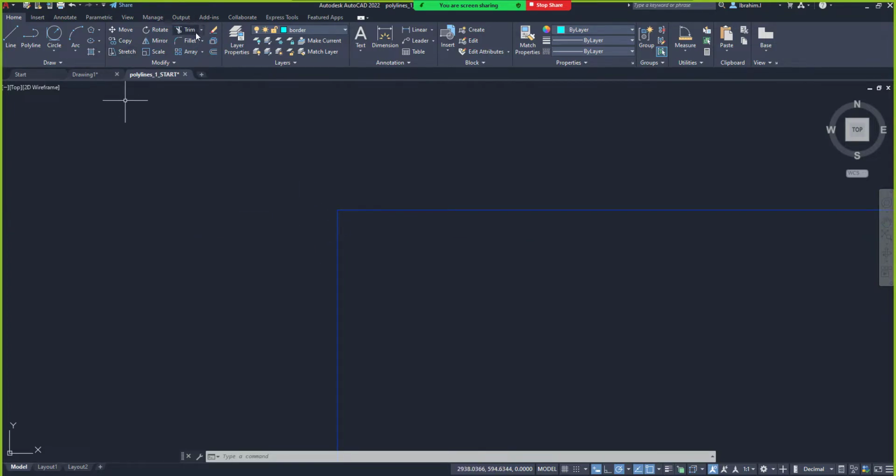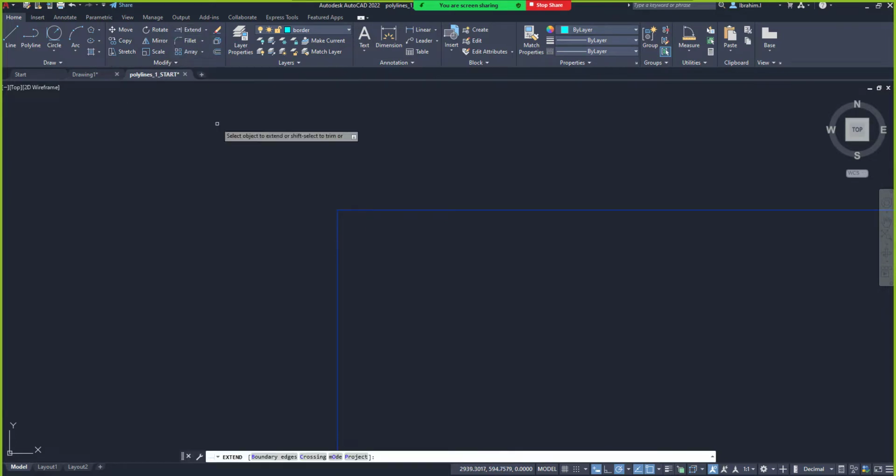Immediately I go to my file, can you see the trim command here under the modify panel? When I click on the drop down, we have trim, we have extend. Are you with me? When I go to my extend command, immediately I select a particular line, it goes ahead. Can you see that it's touching the next one? I've not even clicked yet. I'm just placing my mouse on it. When I click, that is when I tell AutoCAD that this is what I want. Then it is done. Can you see that?